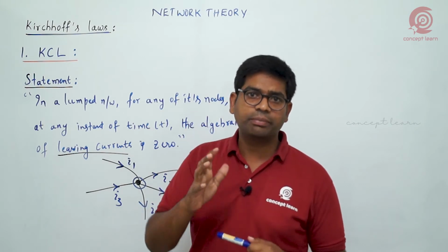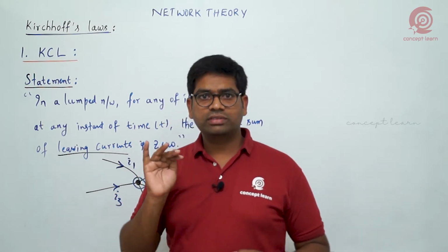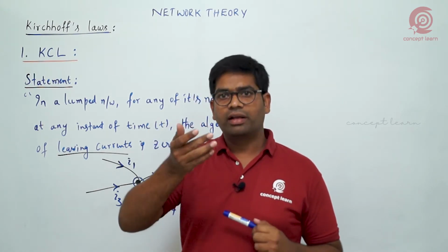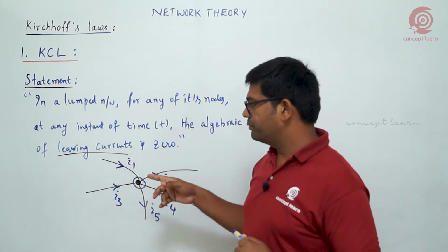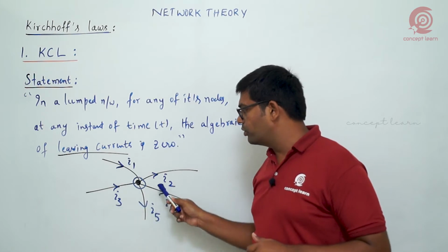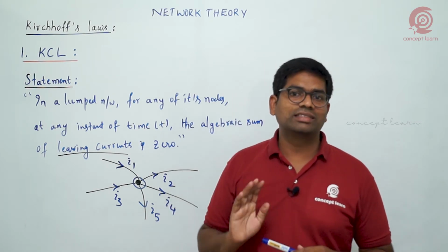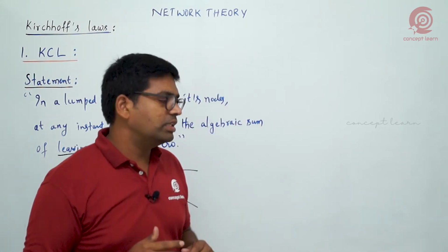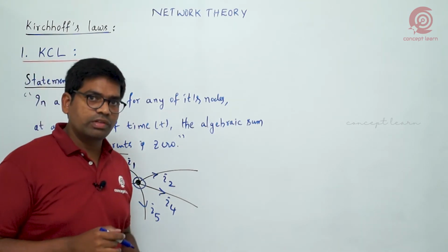Vice versa. You can choose any polarity, absolutely there is no restriction, and there won't be any change in our result. Suppose I follow this procedure, every time we'll be following the same direction as well as polarity. What is that? I keep choosing the same notation here. Incoming current I'll choose with a negative sign, outgoing current we choose with a positive sign. This is the procedure we follow in all these examples. Whatever topic we discuss, we follow this kind of notation. Incoming I am choosing a negative sign, outgoing I am following with a positive sign.